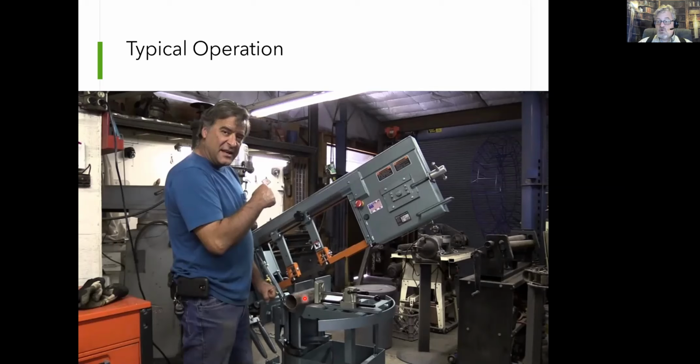You obviously need some coolant, you need some oil to do this consistently and do it well. The coolant flows around the blade and keeps the blade lubricated and cool. The way you keep the length consistent is you put a stop on the other side of this length of stock, and you push the stock up against the stop.